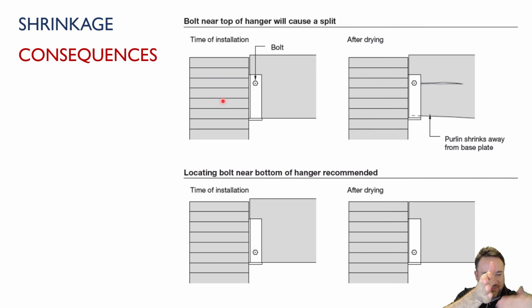Okay, so here's your glulam beam, and on the other side of it, you have a joist that is attached to the side. And that joist is connected to the beam using this steel bracket. The intention here is that the joist sits on this steel bracket. It's got a seat. This is a steel seat here. So the joist sits on the bracket. The bracket transfers that load directly into the side of the glulam beam. And this bolt up here is just to keep the joist from being unseated from the beam. So it's just kind of keeping it in place. It's not intended to take any load. It's just for safely keeping everything where it's supposed to be.